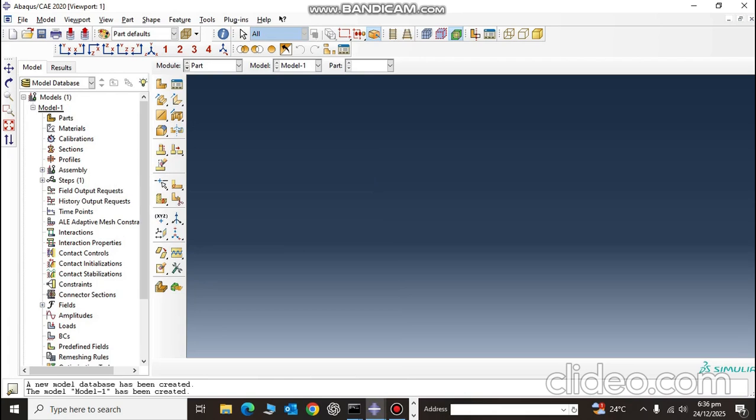So there are basically two methods. The method is the cohesive zone method, and it is divided into two ways. The first method is called the cohesive element modeling, and the other method is called the cohesive surface modeling. So today we are going to talk about the cohesive element modeling. It is a widely used model type in composites and in delamination. So we are going to thoroughly discuss the process of setting up this simulation.